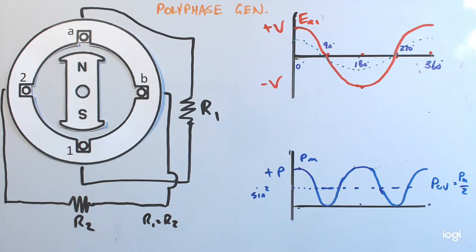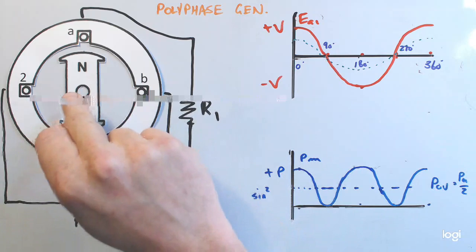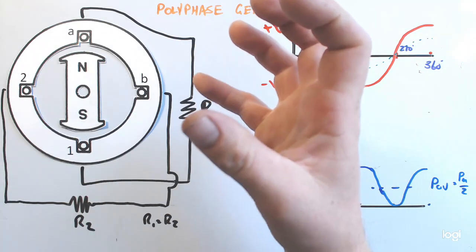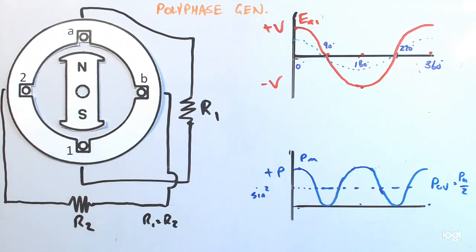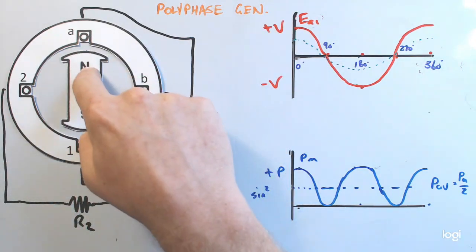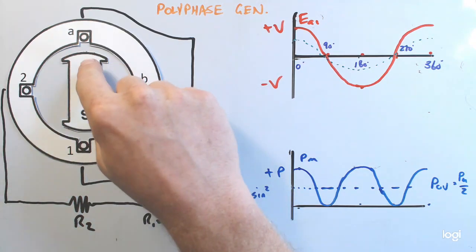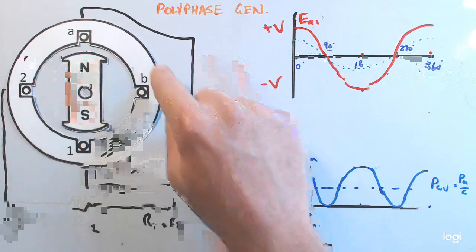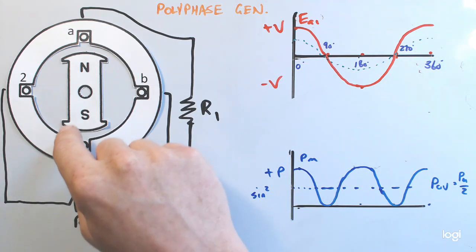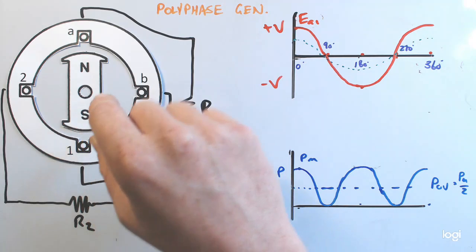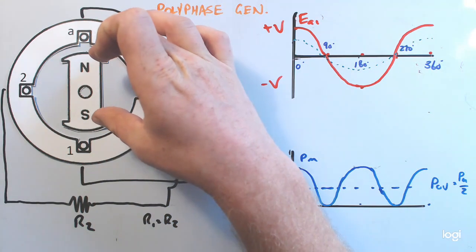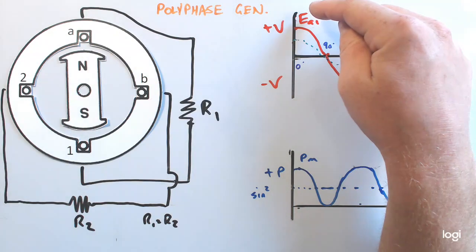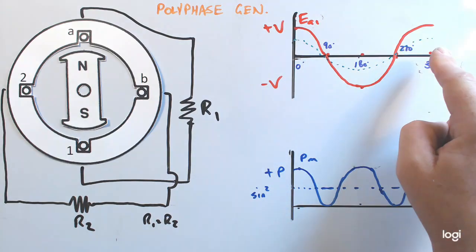Okay, so here I've got the same rotor that's rotating on one common shaft, and something different is happening to the two different coil slots as that rotor rotates. Right now, in this position that the rotor is in, you recall that the magnetic flux lines are leaving the North Pole. They're crossing coil slot A. They're traveling through the stator, and they're traveling back into the South Pole of that magnet. So at this position, we're going to call that position 0. We're going to have the largest peak induced voltage on coil A1. And that's what's indicated here on this graph.